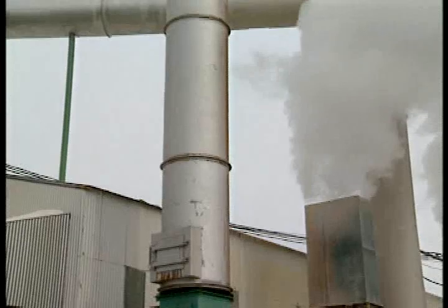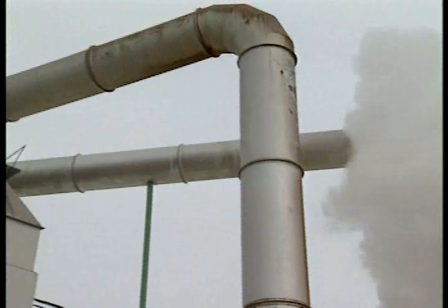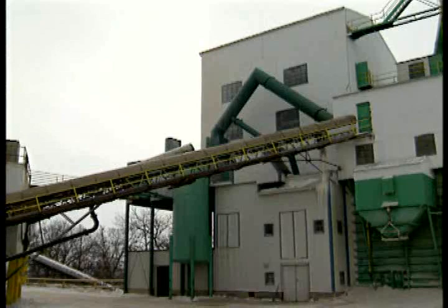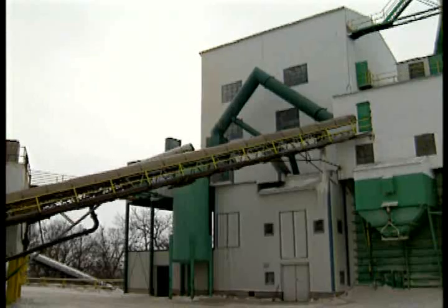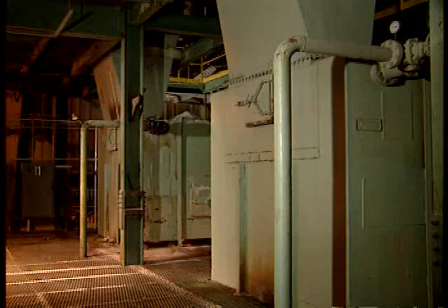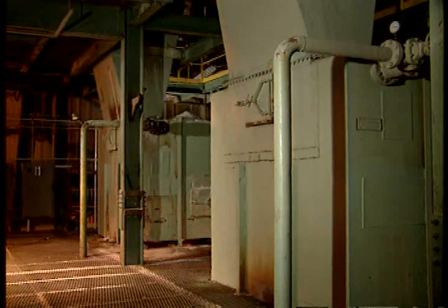You can see the special ducting that we have to take the large volumes of air necessary to burn the fuel we use and to carry the dust away from this area. You can also see the special type of ducting we have used that allows the large particles to fall back into the dryer while conveying the fine dust particles to our dry dust collector. Yes, and I understand that there are other techniques like scrubbing that can be used to do the same job that the dry dust collector does, which would reduce the exposure to workers even more. Yes, we have a wet scrubber in another part of the plant which does essentially the same job as our dry dust collector does on our dryer.